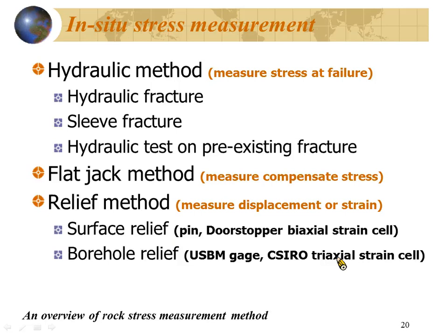And you will try to measure the displacement from the marks or the strain gauges. After you relieve the stress, you will cut the rock, take a sample out, and make it free to move. Okay? So you need to do a lot of very precise work on this.